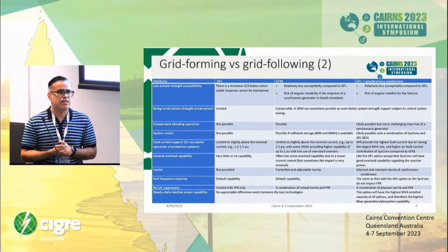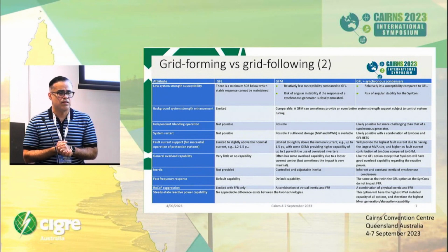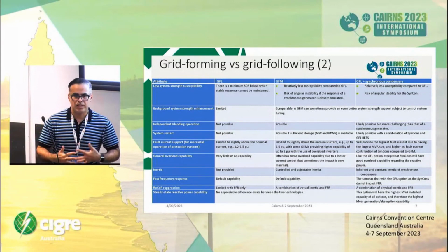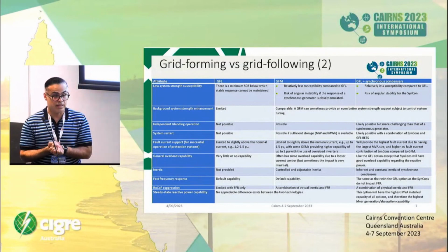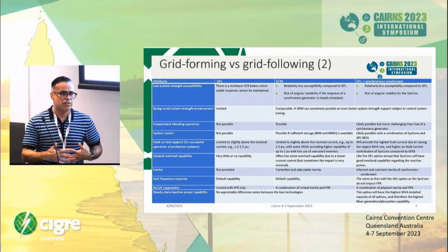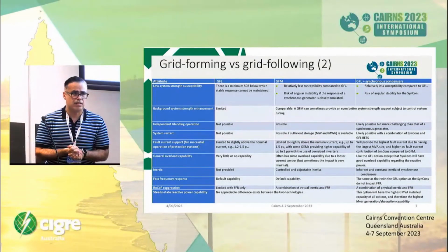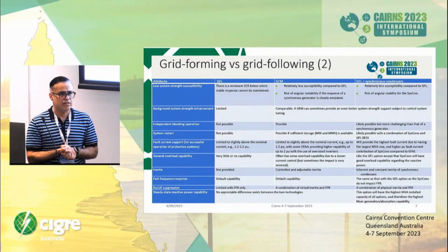And the second question is that if you are bringing whatever the source is, a synchronous generator or a grid forming inverter, the objective of system restoration is not to energize a single component. We know that all these devices can self-start themselves. But what then? System restoration, as I will show a little bit later, is to do with energizing an end-to-end power system, and the assumption that drives developing system strength procedures is that there is zero fault level available in the power system that you are energizing.